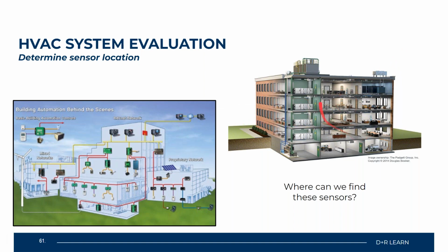Remember, we spoke about our room temperature sensors or room humidity sensors. We'll find these items inside of our facility directly on a wall located inside of that zone or that space. Our outside sensors, like I said, for example the outdoor ambient temperature sensor or relative humidity sensor, will be located at some point outside of our facility, so that we can measure those different measurements.